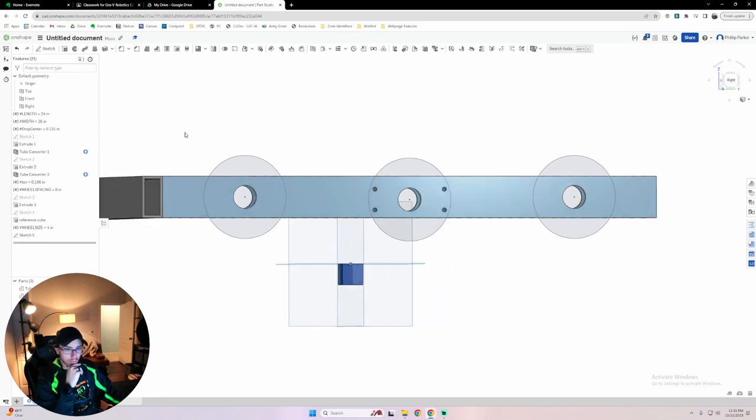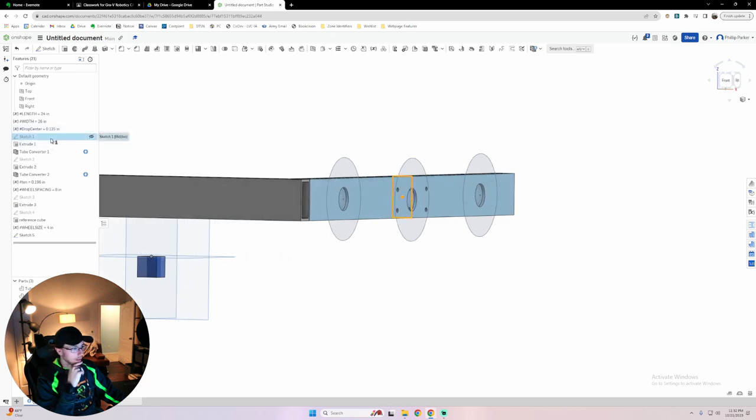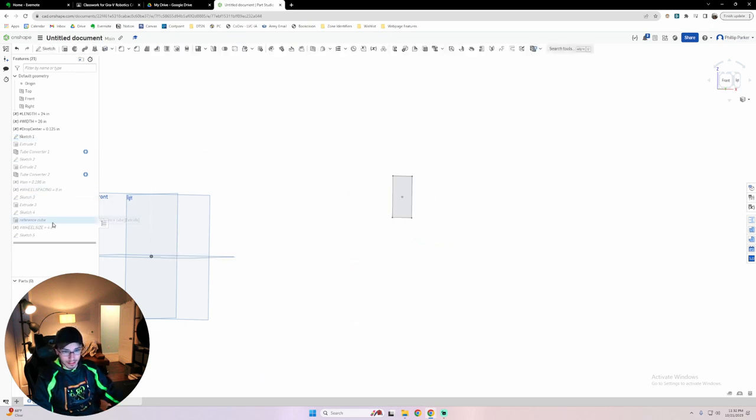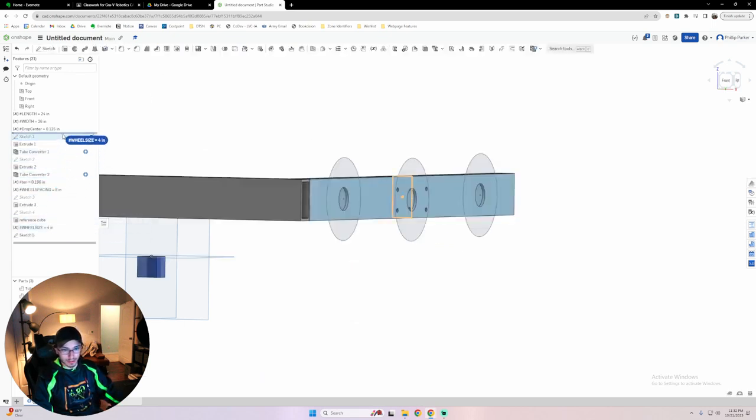I need to modify my height indication here to be wheel size, but I can't because it doesn't exist yet. So I need to move my variable to the top. And just so that I have no more conflicts, I'm going to move all my variables to the top.